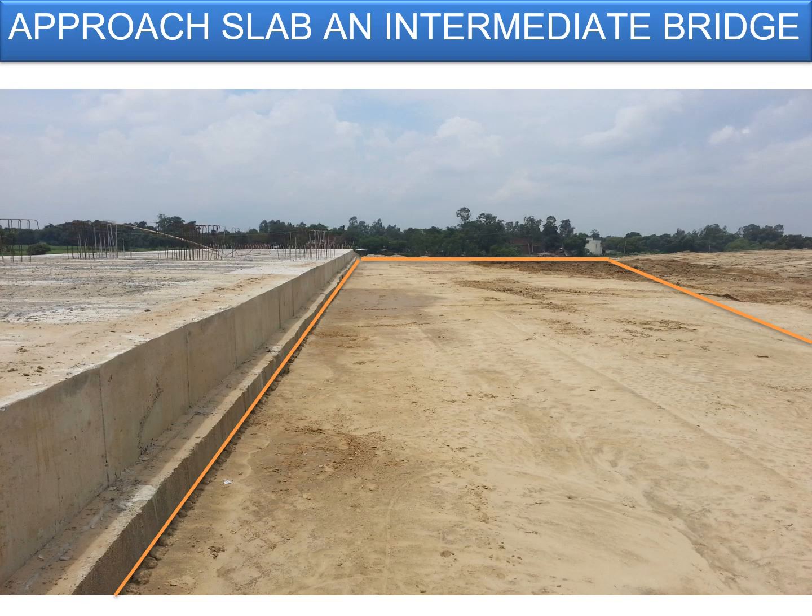For example, if you see the photographs, on the left hand side you can see the face of a structure, maybe a PUP or VUP or a bridge structure, showing one end of the structure. On the right hand side, the line demarcated with an orange line shows that when the road is being constructed, it has been constructed up to the right orange line initially along with the main carriageway, and then this gap demarcated with the orange line is filled up after the completion of the bridge. So this is the portion which is actually an intermediate span which is getting filled up after the completion of the bridge.